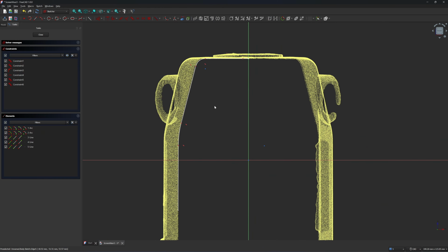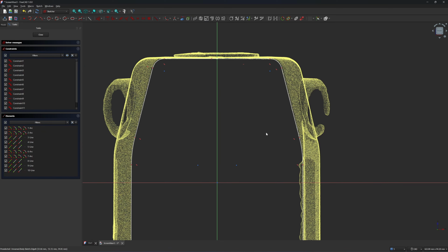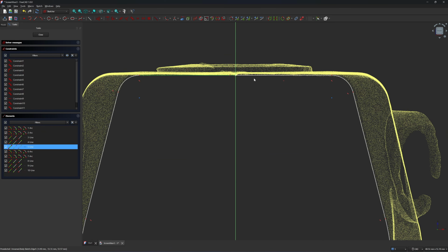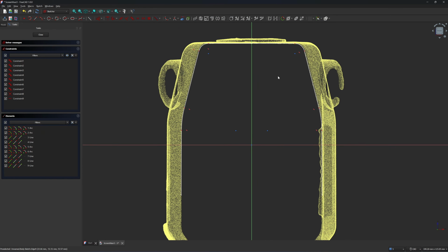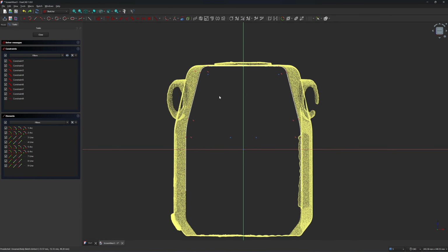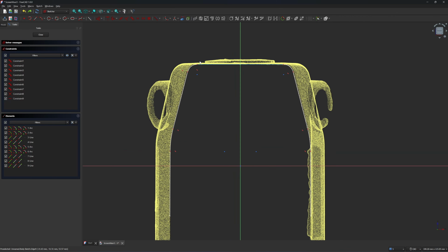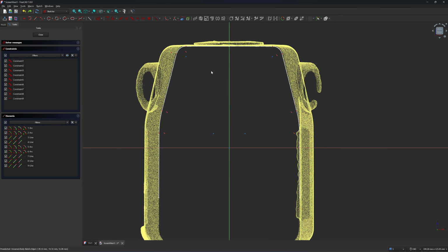Okay, let's do it one more time. Select this line, mirror it. Okay, now it's perfectly mirrored. Okay, I will remove these two lines and make it just one single line, right? So this will be a boundary line. I will offset this line by 0.2 millimeter. So I select all the lines here and then I'm going to click here to offset it by 0.2 millimeter. So I have some clearance when it fits into the body of the scanner.